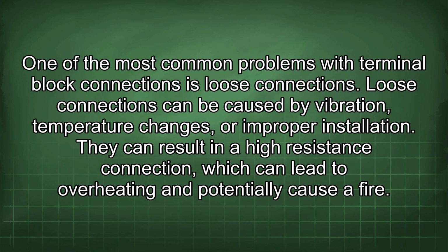One of the most common problems with terminal block connections is loose connections. Loose connections can be caused by vibration, temperature changes, or improper installation. They can result in a high-resistance connection, which can lead to overheating and potentially cause a fire.